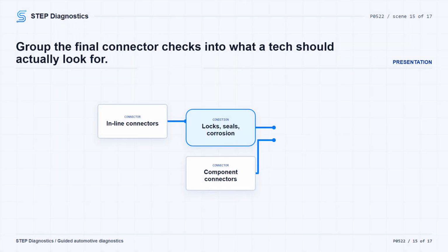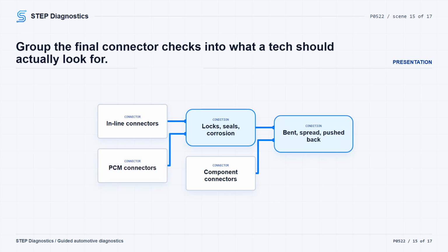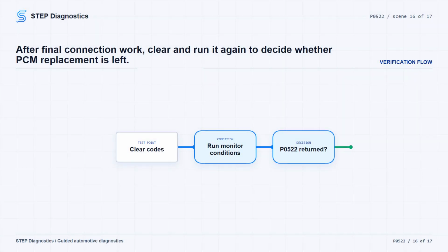If the circuit and sensor simulation checks did not prove the fault, handle any applicable bulletins, then inspect the PCM and related connections. Disconnect the PCM connectors, related inline connectors if equipped, and related component connectors. Look for connector installation problems, damaged locks, corrosion, signs of water intrusion, weather seal damage if equipped, bent terminals, overheated terminals from poor contact, push-back terminals, spread terminals, and poor terminal tension.